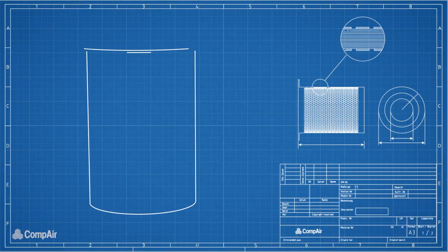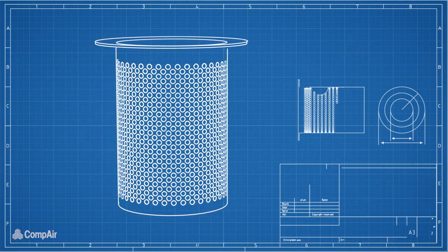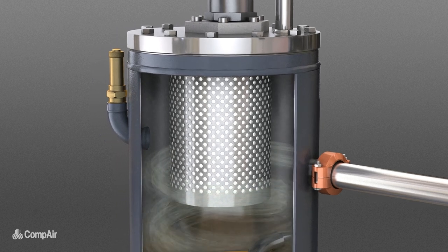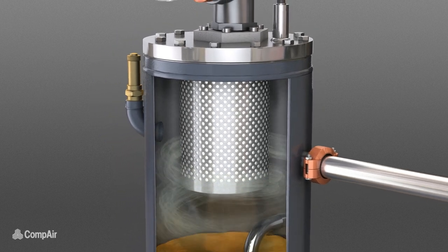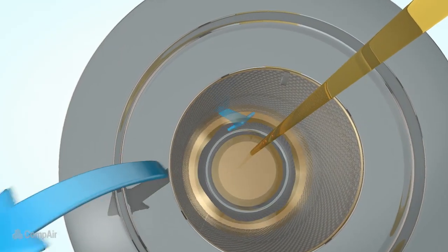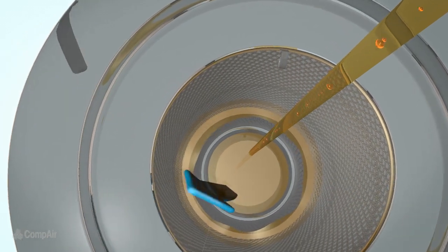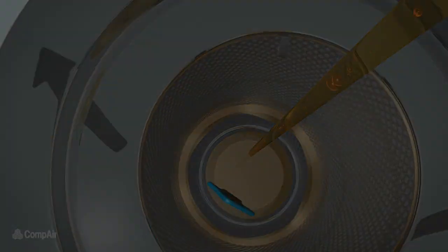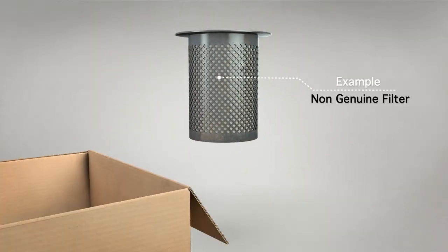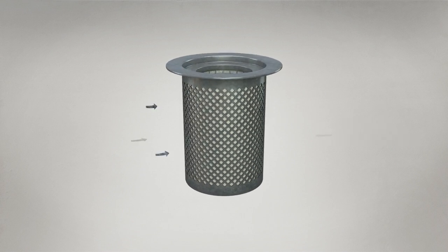In the interest of both cost and safety, it's vital that the air oil separator in your compressor exactly matches your machine's requirements. Essentially, air oil separation is the final filtration process within an oil-lubricated compressor. Its function is to extract and liquefy the oil present in the compressed air vapor and return it back to the air end. However, things may not go to plan if this critical component is made from substandard materials or contains unsuitable filtration media.